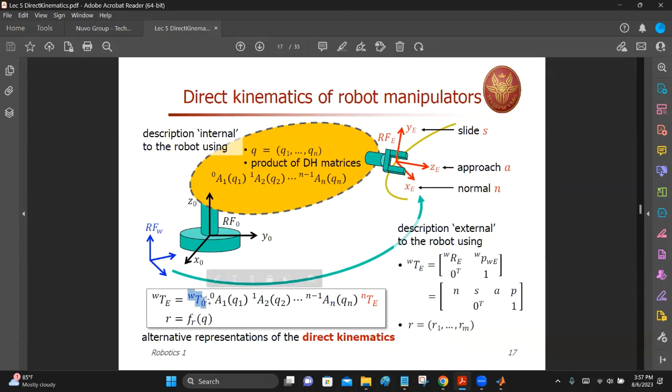You have to physically measure the distances and orientation differences if there's any, and you have to manually fix that for each manipulator in your workspace, and it's a fixed transformation. And every manipulator, when you purchase, it doesn't come with the end effector generally, but certain manipulators specifically designed for a particular application actually come with the end effector.